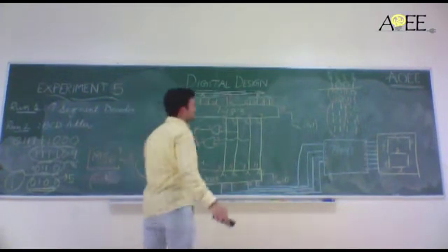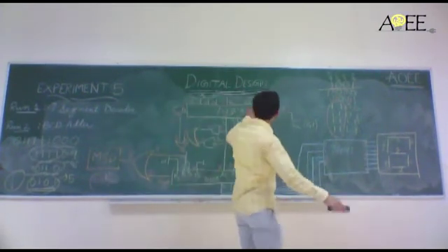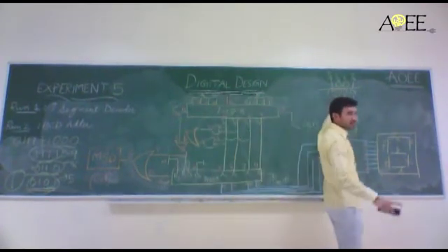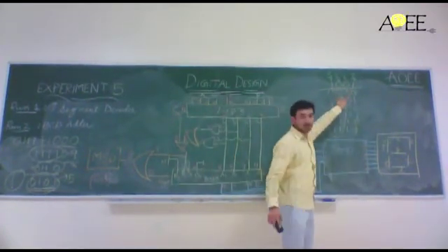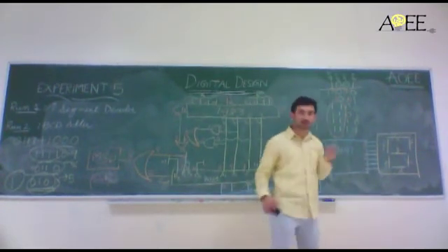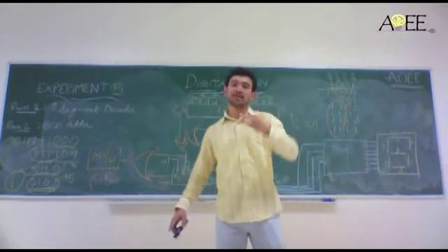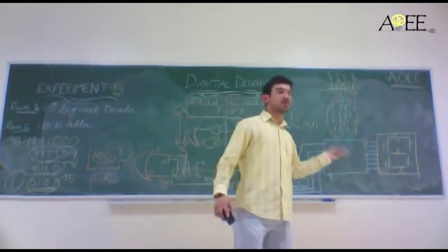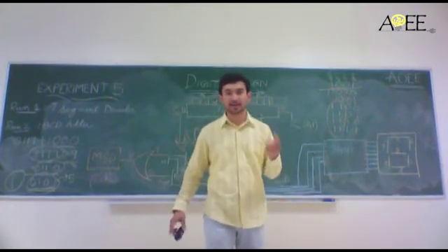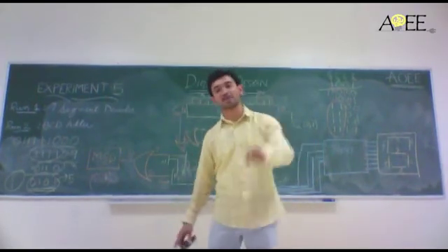So the logic can state that if I have a carry in my initial sum, or S3 and S1 are equal to 1, or I have S3 and S2 equal to 1, in any of the three cases, then I have a number greater than 9. Now, if the number is greater than 9, then obviously 6 has to be added to it.